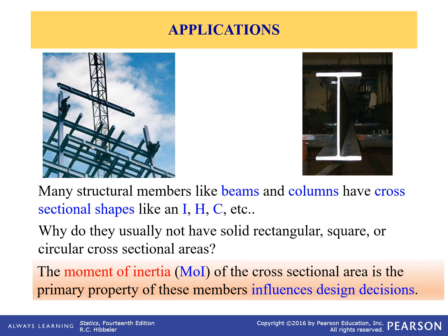Again, we want to have less internal stress and deflection, and the moment of inertia is the resistance to the internal stress and deflection. So we want to have a higher area moment of inertia, so that we'll have less internal stress and deflection developed in our structure.